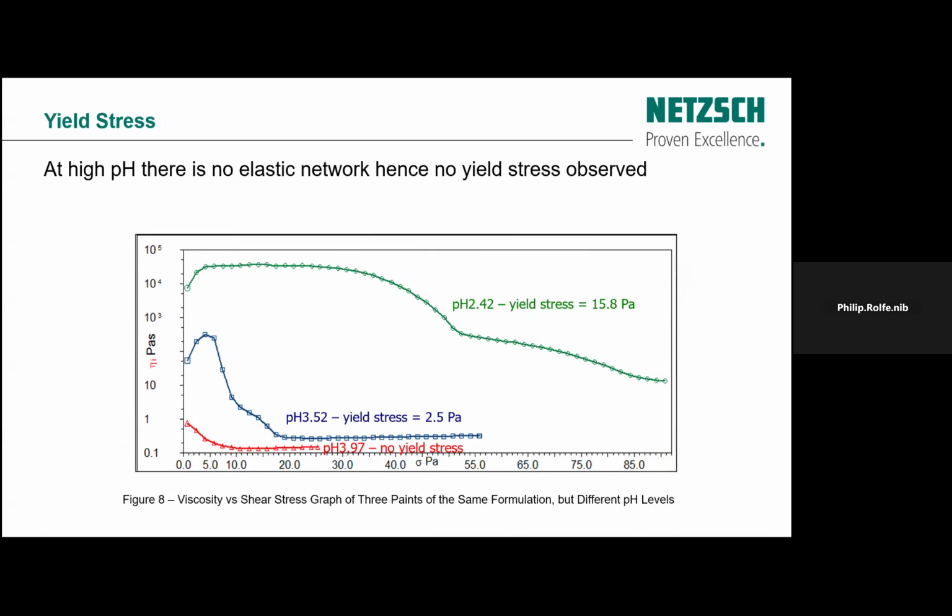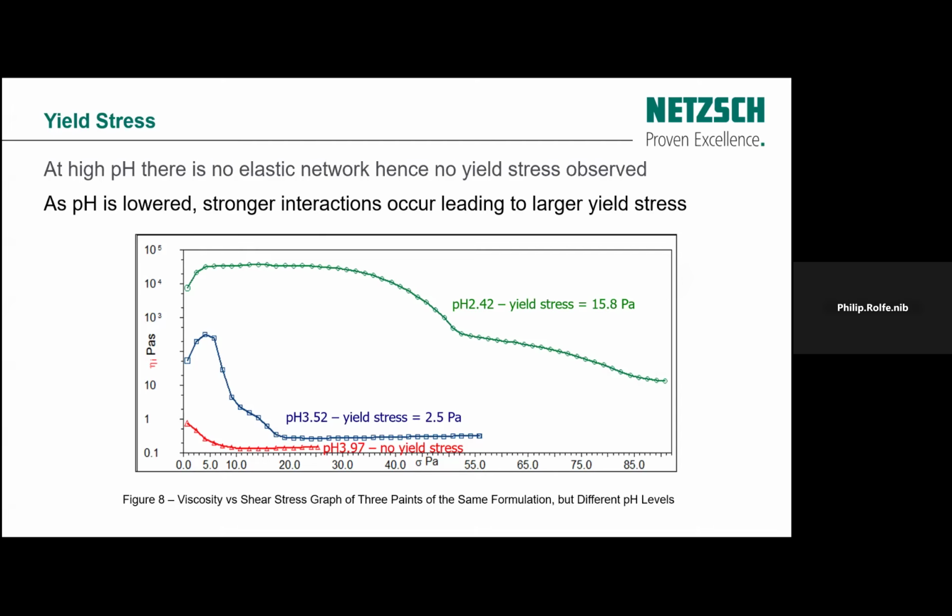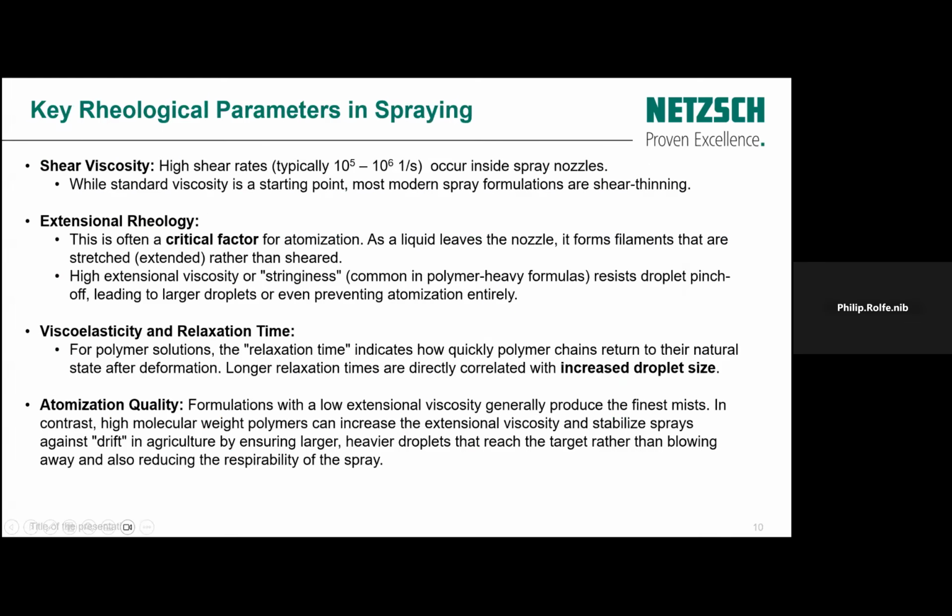So there's different ways of thickening up materials. Obviously, you can add guar gum and things like that to thicken up suspensions. Or sometimes you can just do it by changing the pH and bringing it near to the isoelectric point, if they're more than a micron in size. If they're less than a micron in size, you need to stay away from the isoelectric point to stop them agglomerating.